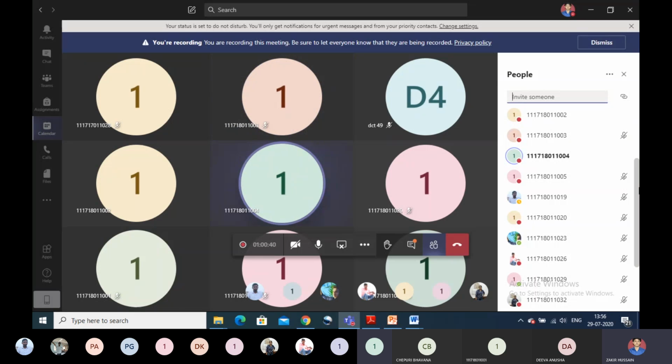The relationship between fluxes: N_i equal to N_xi plus J_i. Then Fick's first law of diffusion: N_A is equal to minus D_AB dou C_A by dou Z. It's not N_A, it's J_A. Okay. Next one, number 5.